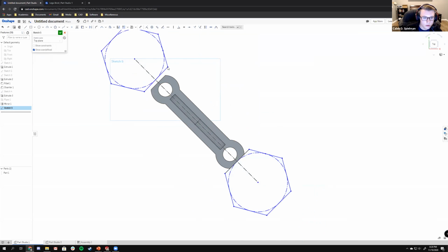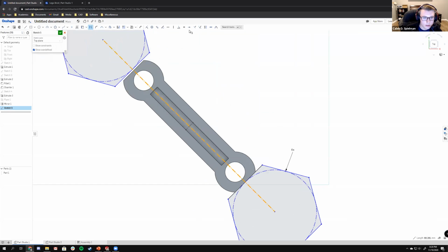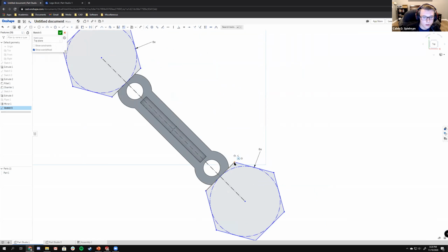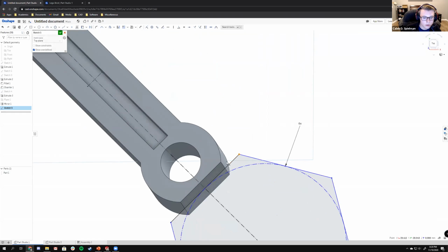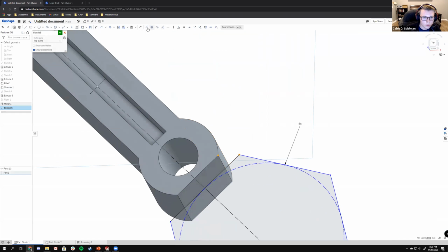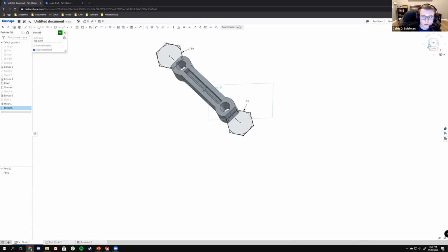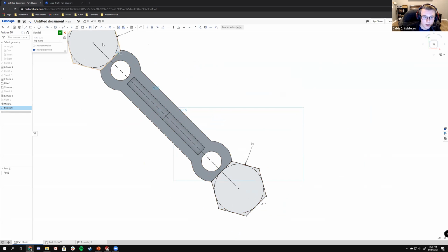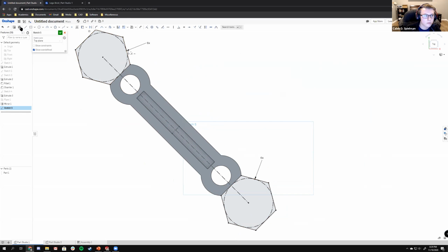Okay. So let's actually select, where is it? Oh, never mind. We can do this instead. Okay, so now we're going to select this line and make this coincident. And then we're going to select this point and this point and make it coincident. Now we have 2 defined contours, which is good. Now we're going to do something with them.